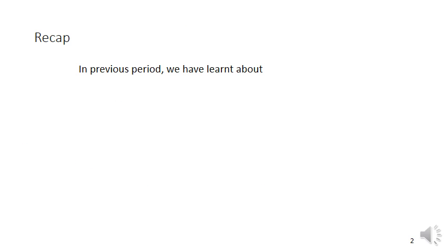In this class we discuss the expression for the work done during the adiabatic process and the relationship between the pressure, volume, temperature. Next, the adiabatic index and some problems related to the adiabatic process. I'm giving the formula for the work done during adiabatic expansion, that is (P1 V1 minus P2 V2) by (gamma minus 1), where gamma is the adiabatic index.